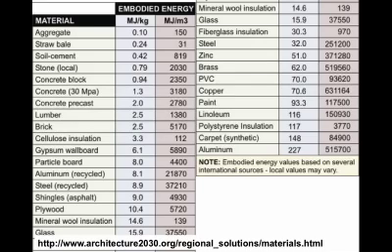So embodied energy is all the energy that goes into producing a product. We have everything from straw bale at 1/4 megajoule per kilogram to aluminum at 227 megajoules per kilogram. It's worth noting you would need the equivalent of about 5 kilograms of petroleum to produce 1 kilogram of aluminum. However, recycled aluminum has a much lower embodied energy because the largest portion of energy for aluminum refinement is extracting the pure aluminum from the ore.